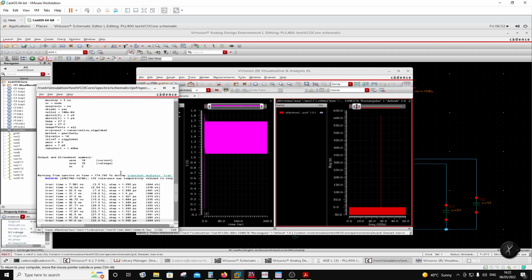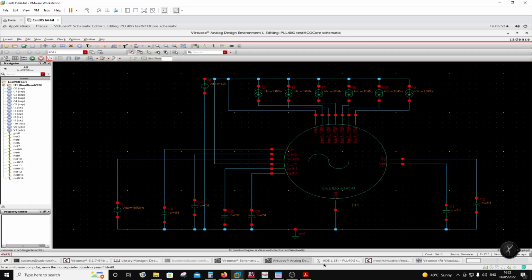So this is the last simulation. This, by the way, is a 130 nanometer CMOS process. This is called Silterra. This is like an 8-layer process with the top layer thick metal of 4 micron. So the inductor Qs can be good. And I have put in the inductors with the appropriate losses in this design. Later on, I'm going to simulate each inductor and put in the realistic losses and adjust the performance.